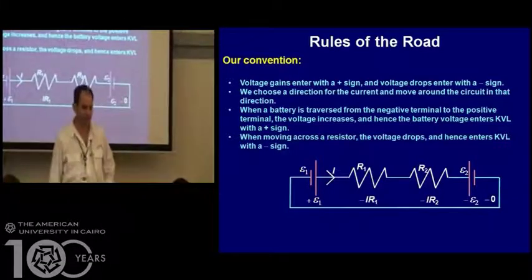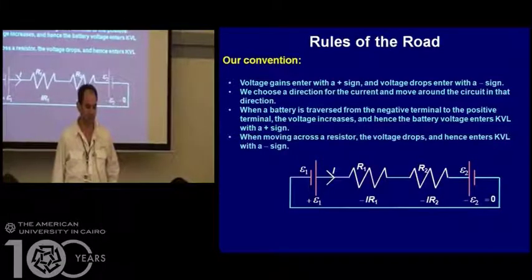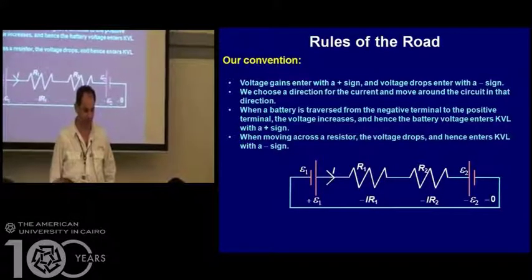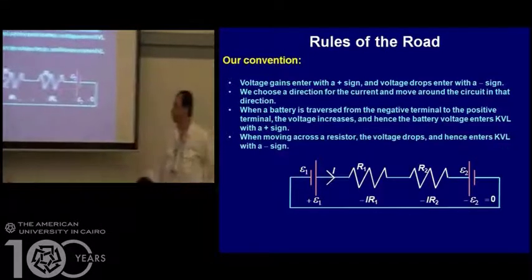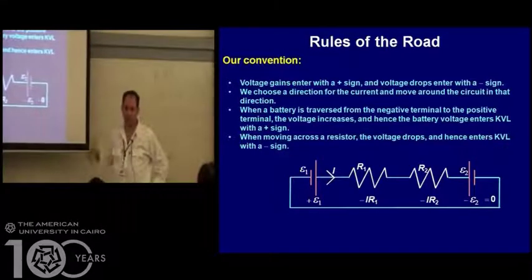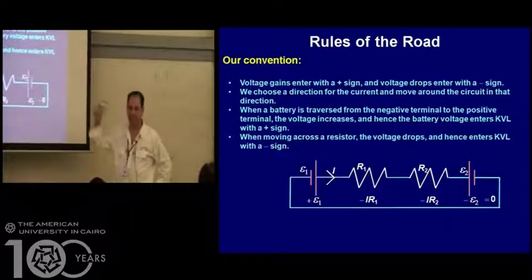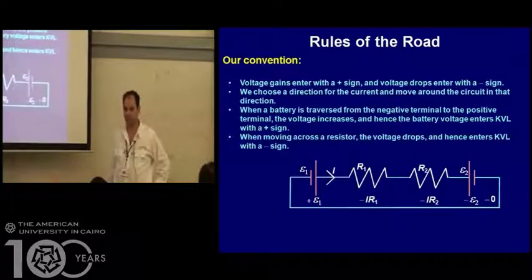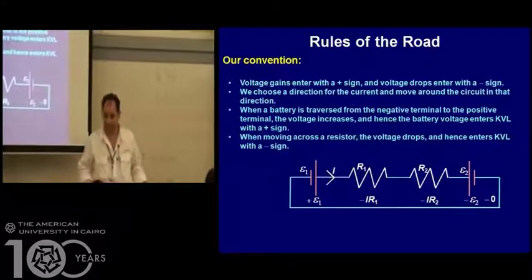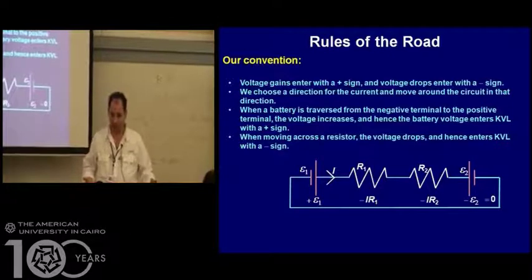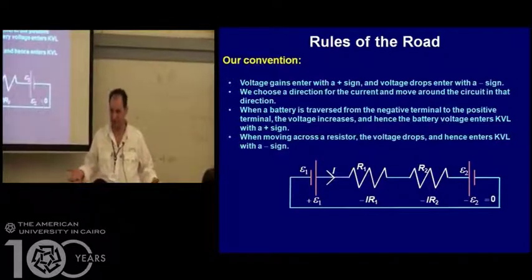The higher potential, the higher battery potential, will force the I to be in its direction. Even if I1 is less than I2? It cannot be. This is a series connection. The current in the circuit is the same. The current in the loop is the same. I mean the current from each battery. It cannot be. A lower potential will produce less current in a way.